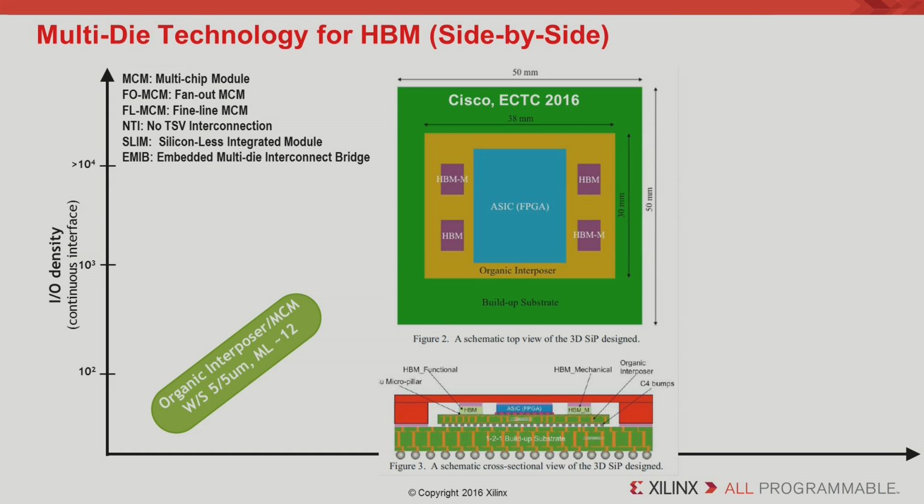In this case, 10-micron pitch is the minimum rule. So you end up needing probably about 8 layers or so to hook up the SoC to the HBM if you want to use the full features of the HBM. So what are the pros and cons? The pro is clearly that, from a supply chain perspective, this is a little bit more what people are used to. There's a substrate provider and an assembly provider. It makes it a little simpler. The con is, you still have to worry about things like latency with this approach.